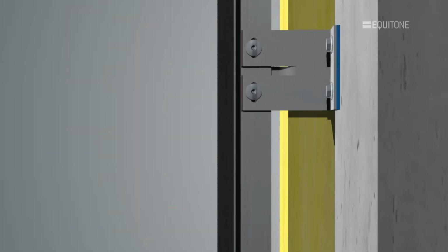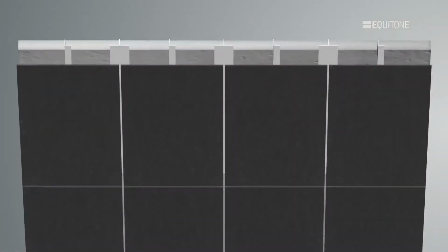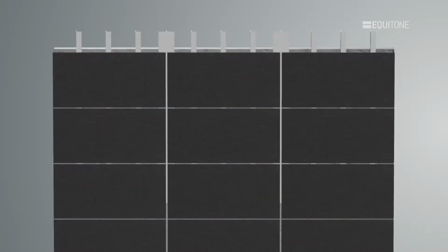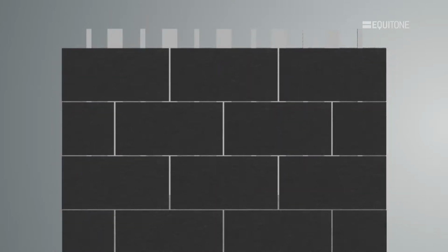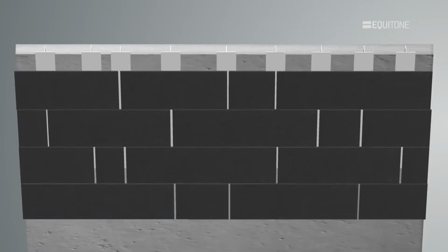The panel layout can have a big influence on the amount of large or small profiles needed. When meeting the architect early in his design process, it can be helpful to discuss this. For example, using the same size panel in a vertical pattern will result in a different subconstruction layout than if the panels were arranged horizontally. Other influences include having staggered joints or free patterns using different sized panels.